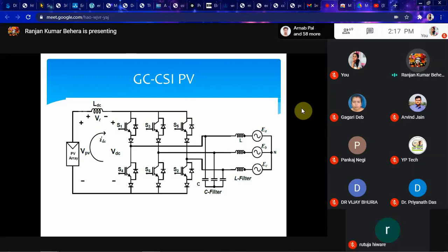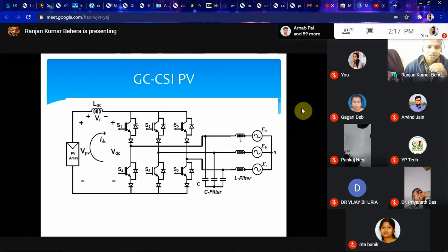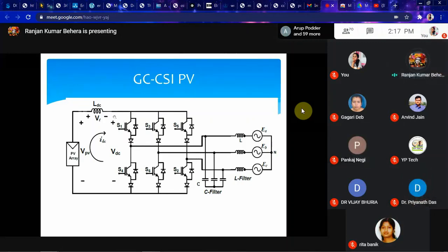So for controlling current, we have a unidirectional switch. You can see after this IGBT, there is a diode connected in series, which makes the complete device a unidirectional device. That means the current will flow in one direction. The voltage can be reversed, but the current cannot be reversed in a current source inverter.